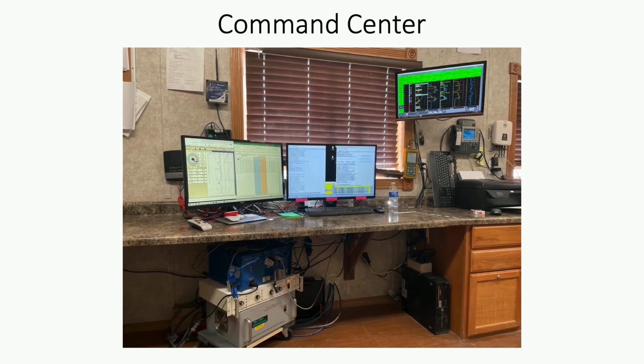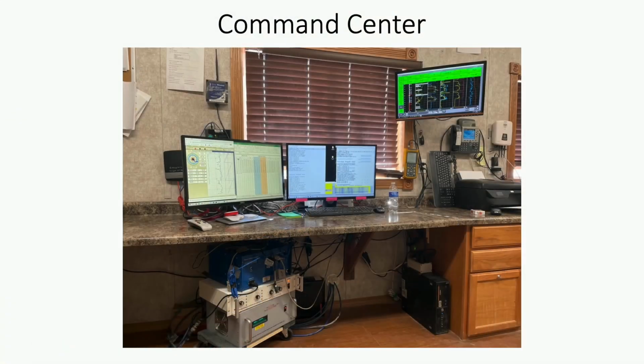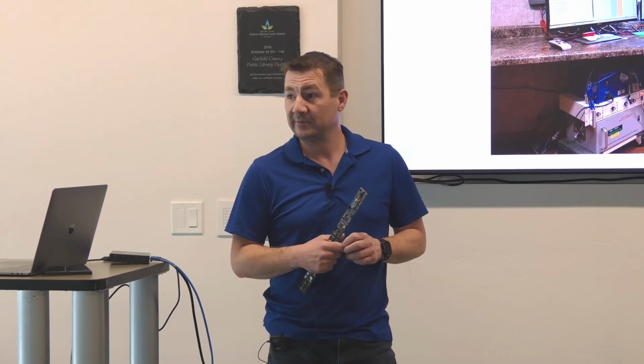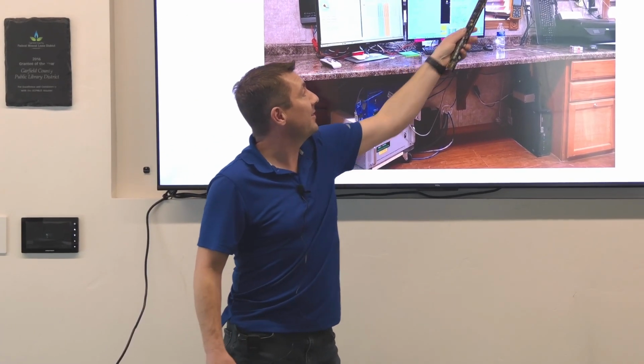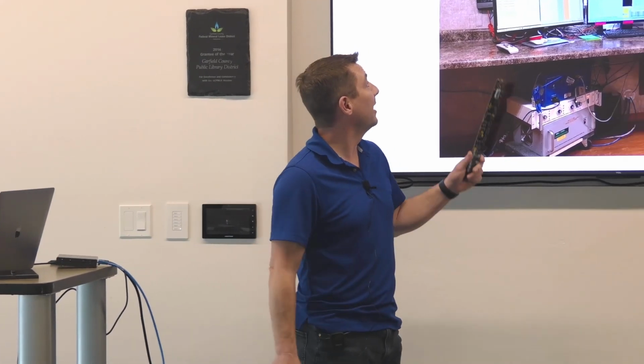This is a picture of my desk. You can see up on top there, I'm watching Payson. I actively have to watch Payson all the time to make sure that the drilling parameters are within spec and that we're not getting too hard on the tool. It's part of my job to make sure that they're not mashing on it, as we say, to get too much shock to the tool, and then it's junk. Are there alarms on that? Yes, oh yeah. Any one of the boxes on the screen, you can set an alarm for. So yeah, we utilize the alarms a lot.